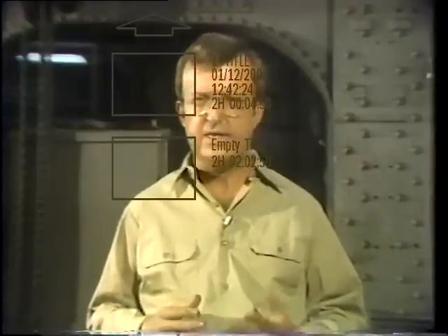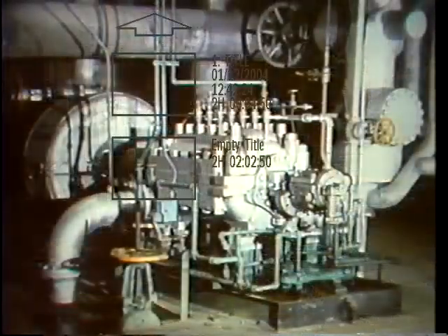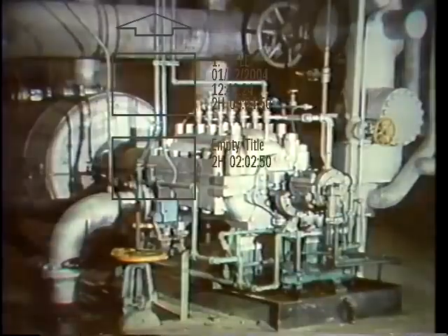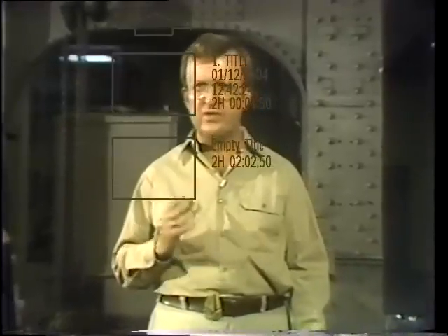The lubricant's surroundings or environment is the fourth factor. Certain lubricants are better in dirtier or dustier areas, and there are other environmental considerations. These include whether the equipment is mobile and what kind of atmospheric conditions exist. You'll need this information to avoid errors and to understand why a particular lubricant is used.